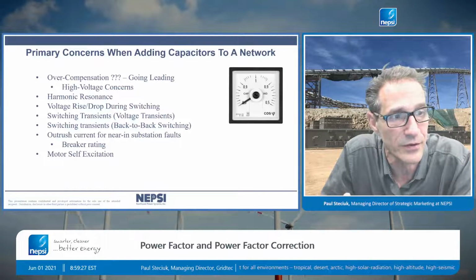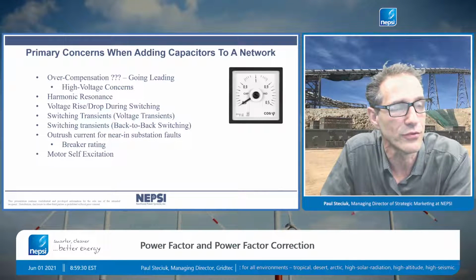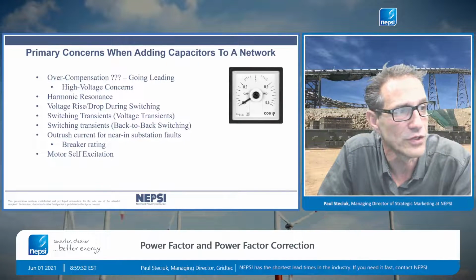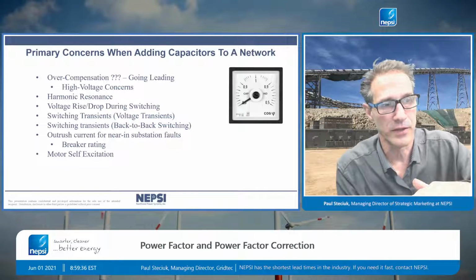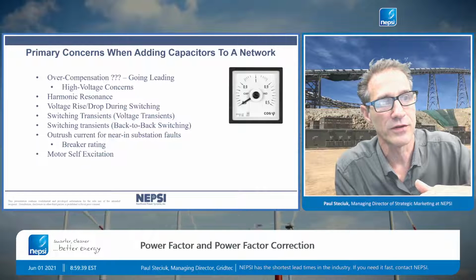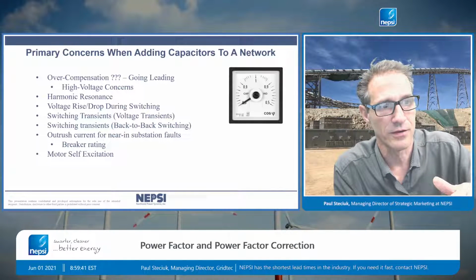Harmonic resonance, I noted that already. Whenever installing capacitors, always be concerned about resonance. Voltage rise and drop during switching. The general rule of thumb is if I switch a capacitor bank on, the standards want to keep me at 3% or less.